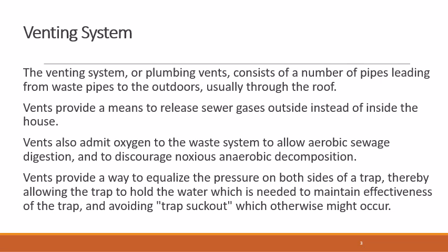The vents also admit oxygen to the waste system to allow aerobic sewage digestion and to discourage anaerobic decomposition. The vents also provide a way to equalize the pressure on both sides of the trap, thereby allowing the trap to hold the water which is needed to maintain the effectiveness of the trap and also avoiding the trap being sucked out, which may otherwise occur.